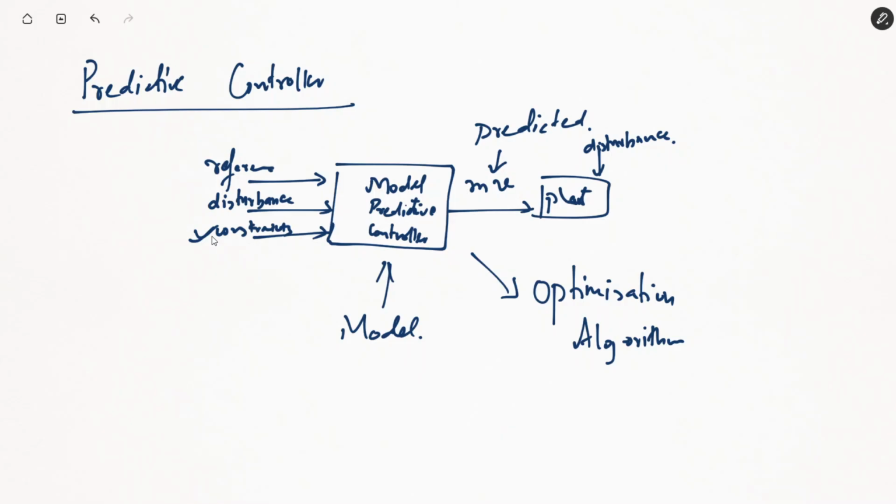Say, for example, we are controlling the speed of an induction motor. The quicker the response of the system, that also means the current in the system will be very large at some point of time before it reaches a steady state value. So if the transient is very quick, if the speed response is very quick, that also means there will be a very high current value that can actually be dangerous for the system.